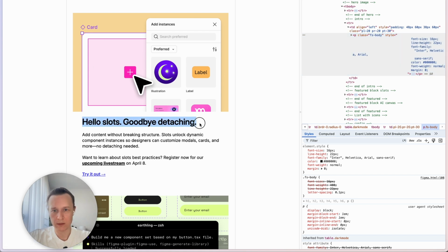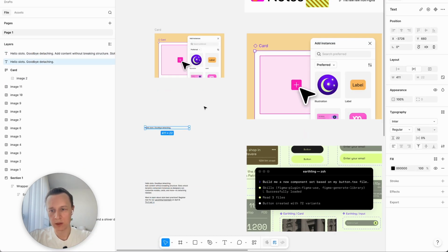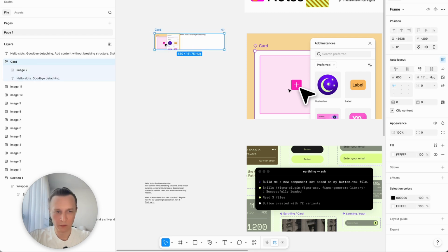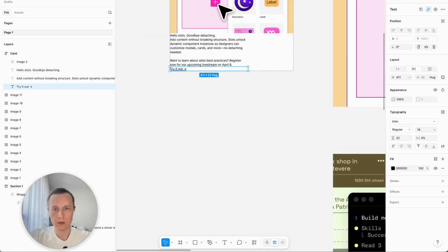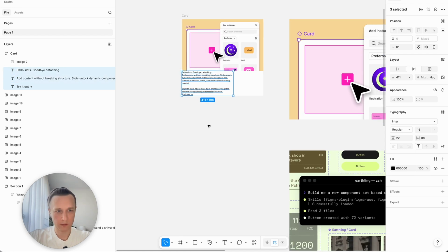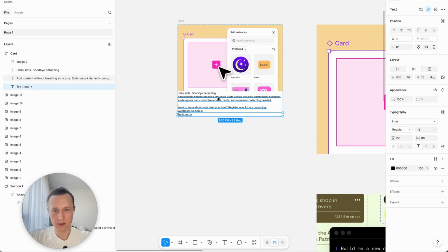and next let's add two texts, body text and button. Let's just put content inside the card, then add some layout later. Do not forget to set vertical alignment. Okay, now we have all the text content. Let's set up a proper layout. To do so, select all the text objects, set fill container, and add some text styles. I will mirror the text styles from the original email.